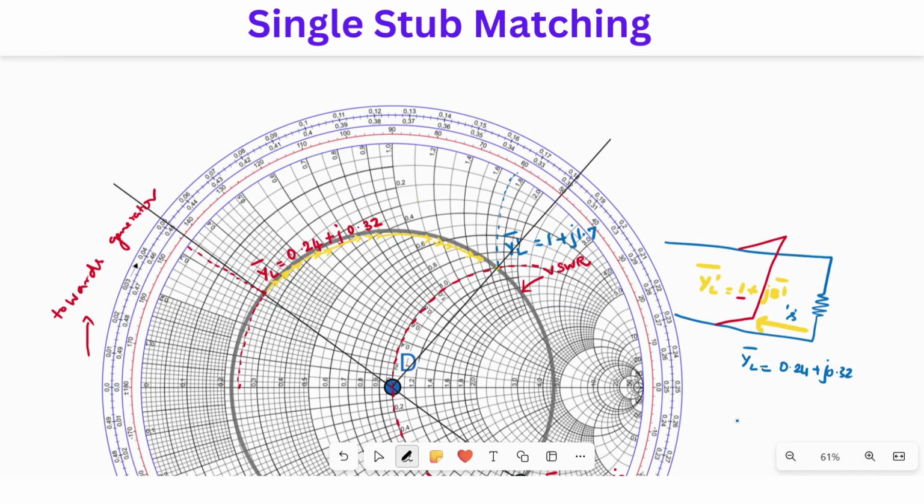I have drawn a line from the center towards the intersection of your unit circle and the VSWR circle, and I have extended the line towards the outside. So the position of the stub is the distance from this point to this point, in this direction. That is our position of the stub.